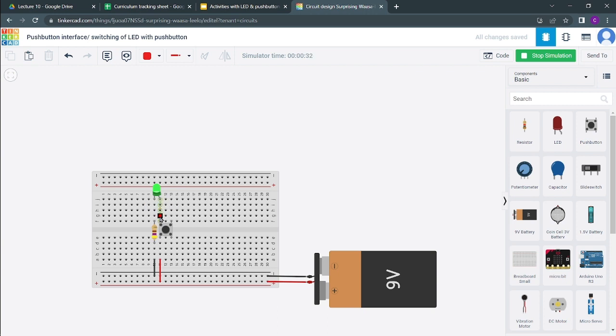To here, we have connected this terminal to the anode, and hence current reaches the anode and then the cathode, and then goes back to the battery's negative terminal. Hence it is a closed loop, and current flows, turning the LED on. Hence you have to connect the push button's diagonal terminals in order to operate it as a switch. So here the interface of the push button completes.